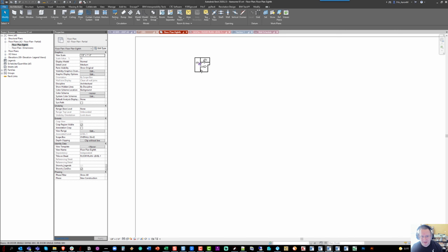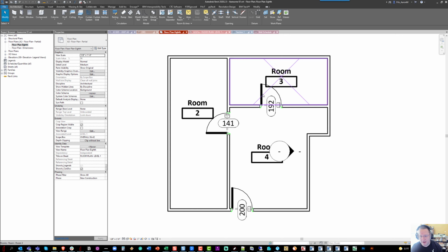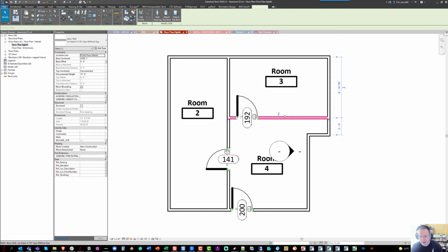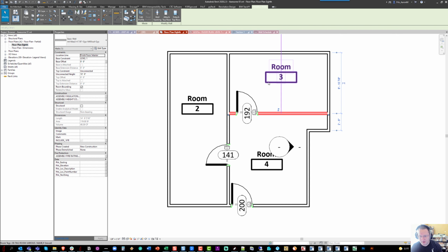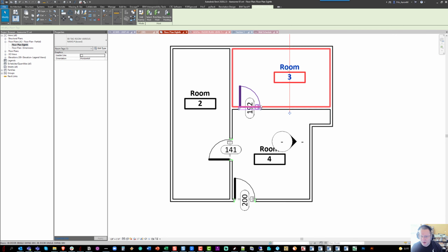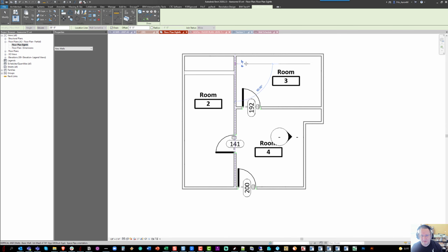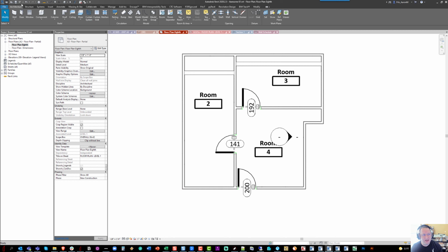So here you'll see I'm in the actual group file, and now I can do things like move the doors around and adjust the walls. And it is true, of course, that I'm making non-destructive edits. It's also true that if you add a new item, there will be a new element ID, and if you were to delete an item or mirror an item without copy, that would also be a new ID, but that's also true in basic Revit editing, so there's no major difference there. So we can throw in a couple of additional walls, and then we can save the file again that's called Awesome01.